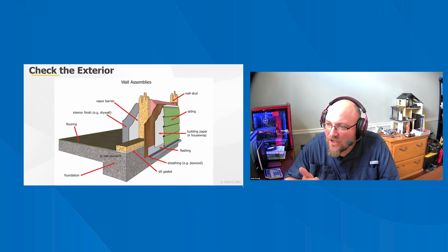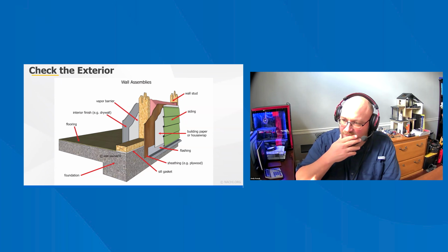One, it is airtight. All air leaks should be sealed in the wall during construction before the insulation is installed in it. Two, it controls moisture. An exterior rain drainage system, an air barrier, and a vapor diffusion retarder should be installed on the correct side of the wall, depending on your climate. And three, it has complete insulation coverage. The wall framing should provide enough room for complete maximum insulation coverage and reduce thermal bridging with no open gaps or compressed insulation and continuous insulated sheeting.